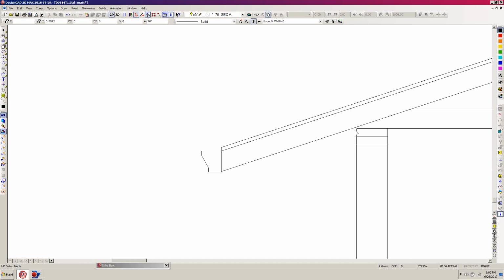You can also see that my wall line doesn't quite touch the bottom of the top chord because of that 1/4 inch butt cut. So I'm going to go ahead and trim that wall line to a butt, the bottom of that top chord. So I'm going to hit E, click near the line, and actually I'll go out of orthogonal mode and click this line, and you can see that it scooted right up to it and trimmed it right to it, just like that.